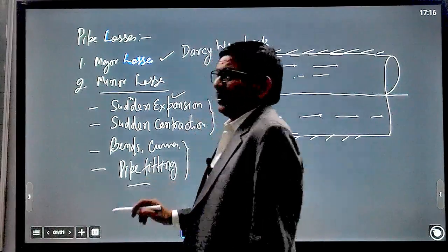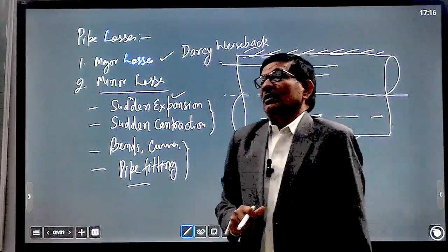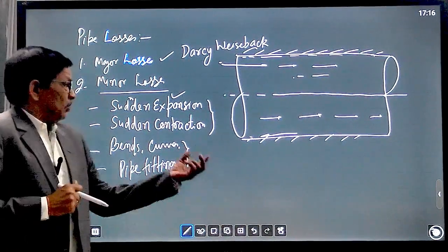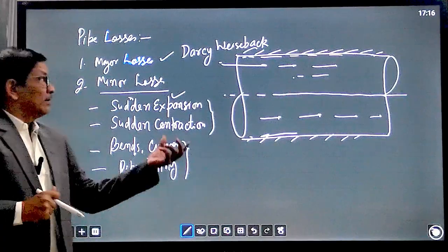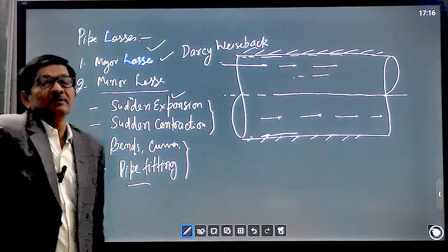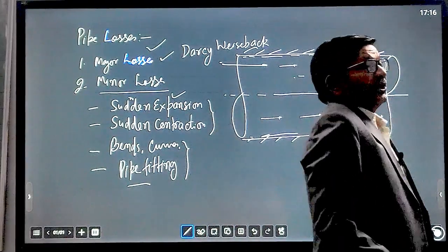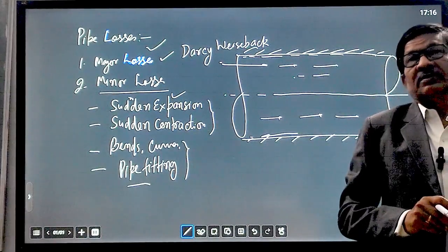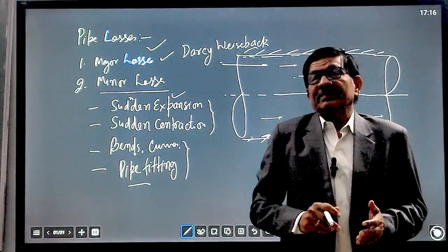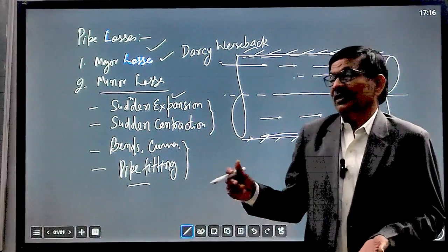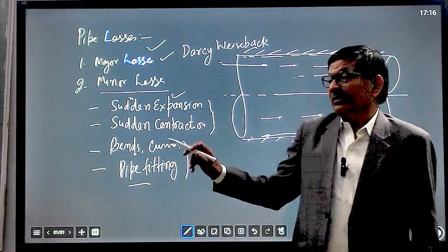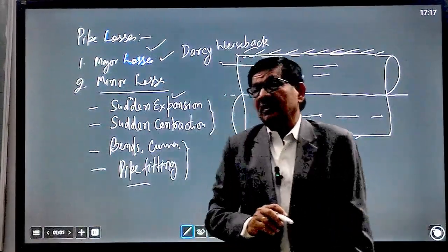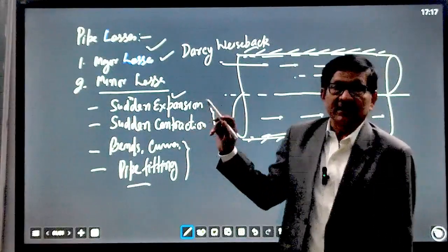Bends and curves. When the pipe is very long, for example, pipes that are used for supply of crude oil over very long distances, these minor losses are almost insignificant compared to major losses. So in that case, we can neglect minor losses. But when the length of the pipe is not very high, for example 10 meter, 20 meter, 50 meter, up to 100 meter, the losses become significant. So they need to be calculated for head loss due to frictional and obstructional losses.